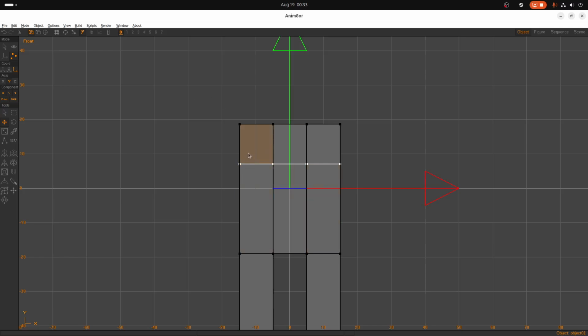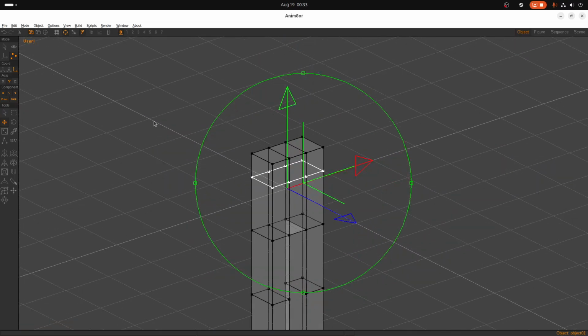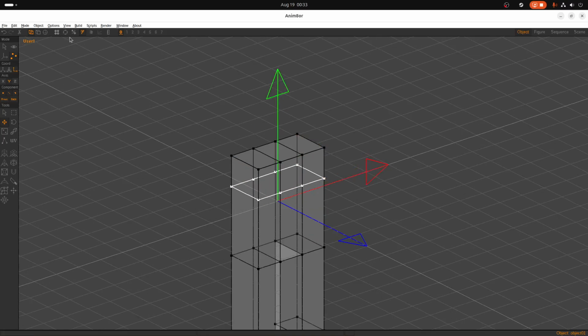Alright, and now on the sides here, you're familiar with this thing I clicked earlier to move around. That's what I used to get to this view. So I'm going to unselect: hit the select tool and click outside the shape so that it unselects everything. Now you've got to be careful not to select the point or the edge. You want to select the face like this.